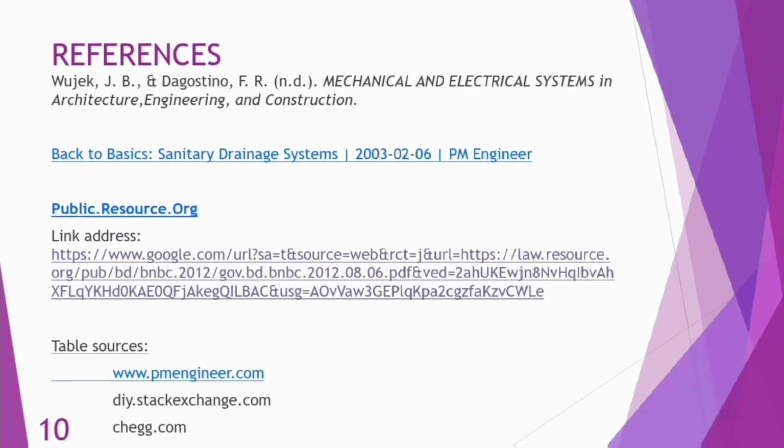In conclusion, we could say that there are 3 vital concepts of building drainage systems and components, and these are the slope of the drainage system, the drainage fittings, and the sizing of the sanitary drainage system. If these 3 concepts are done properly, we could say that it will lead to a better functioning and a reliable sanitary drainage system installation, which allows the free flow of water, prevent the accumulation of stagnant water which can encourage mosquitoes to breed, as well as promotes a healthy environment for the employees.